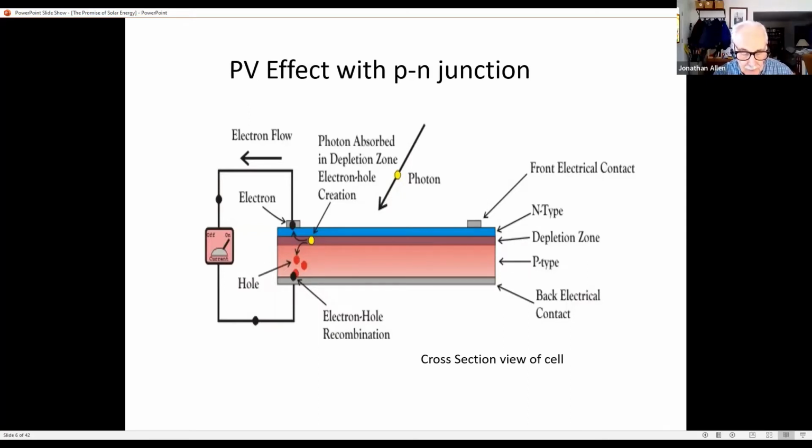Since conduction electrons are able to move about, one can jump into the vacancy and leave another vacancy. Thus, the hole can effectively move about. Think of an underwater bubble, which is actually a vacancy in the water, that can be thought of as though it were an actual object. The hole is thus an absence of a minus charge, but it can migrate and behave as though it were an actual positive particle.